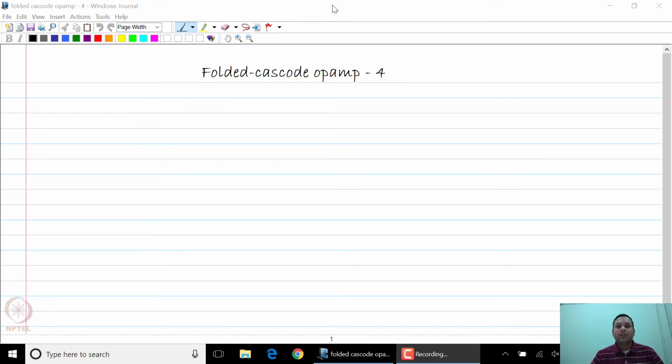In this lecture, we are going to study the folded cascode op-amp a little bit further because there are a few more things to understand about it. The three major quantities that we still have to look at are the slew rate of the op-amp, the input referred noise, and the input referred offset. And finally, we need to build the data sheet of the op-amp in an organized manner as a table. So let us first start off with each one of these one by one.